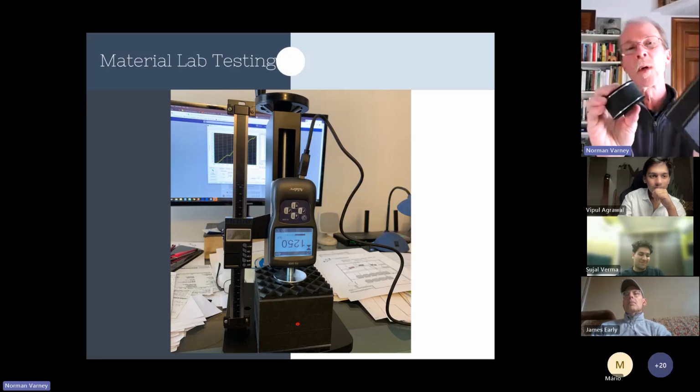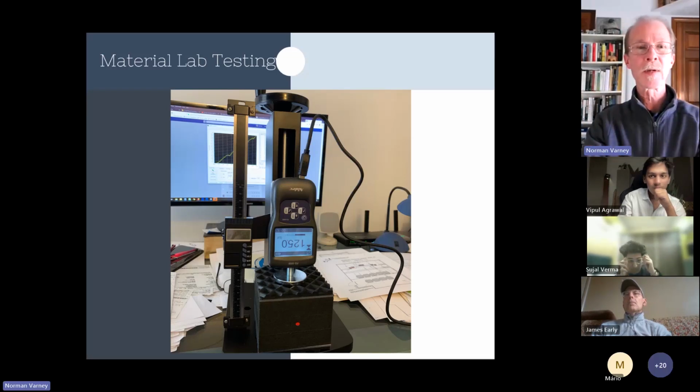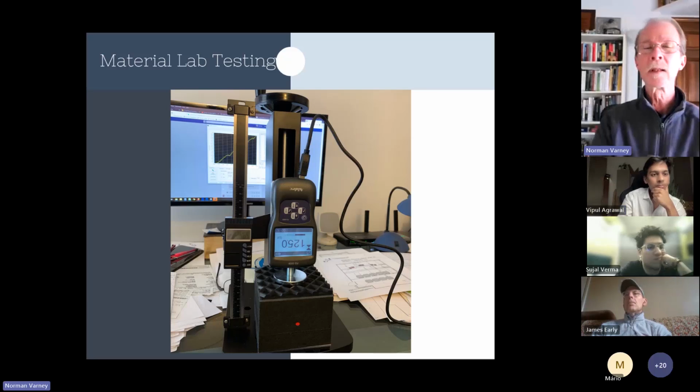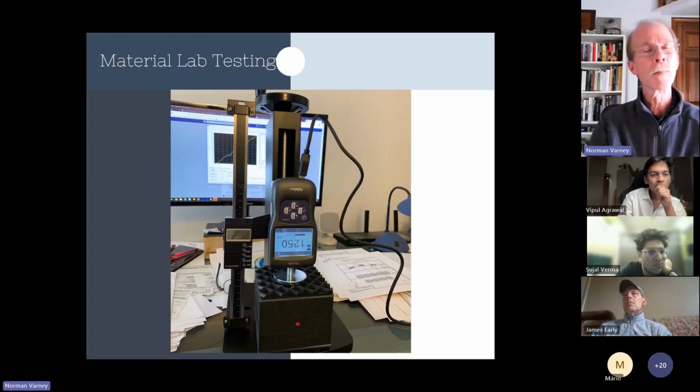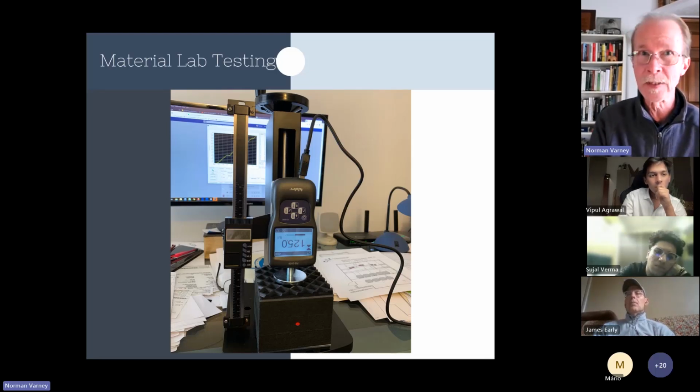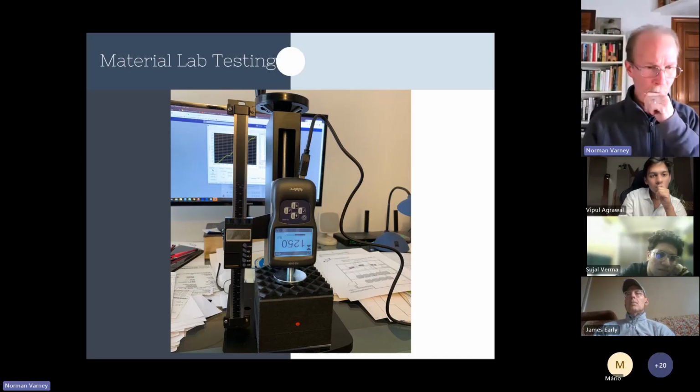There is a video on our website where I do a little demonstration with a music box, so I'll tell you about it. It's layers of fiberglass. The more layers, the denser the material, the heavier the load can be. But the key is, I don't want to have any resonances in the audible bandwidth. So I want to make sure that the natural loaded resonant frequency is at least an octave below the lowest frequency I'm interested in, which would be what, 20 hertz? So I want it to be at least 10 hertz.